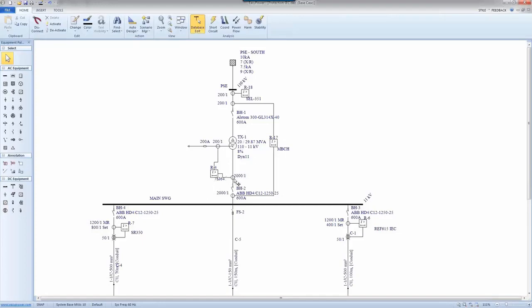numbers. For example, you would see that we have a lot of CTs with a secondary of 1 ampere, which everybody knows is not a common practice in the US. In the US, you would see a lot of 5 ampere CTs. Not that there are no 1 ampere CTs, there are, but they are not as common as in European or Middle Eastern areas. So we tried very hard to reach out to engineers and people who work in those areas to really hear from them and make sure that everything implemented here is really compliant and is common practice in those areas.